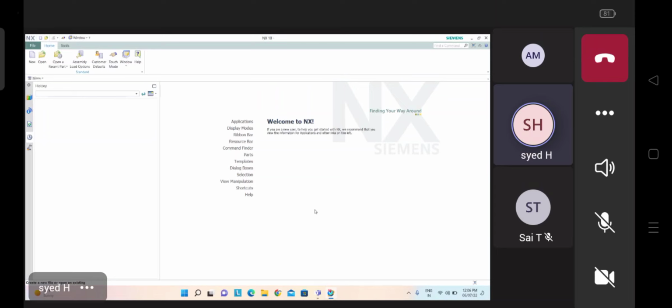So in top down approach, what we will do means we will create our component in the assembly level only, and there only we will do assembly. But when you go for the bottom up approach, we will create the parts in a part level, then we will save in your local library, and whenever we require we can call those components into the assembly level, and there we will do assembly.